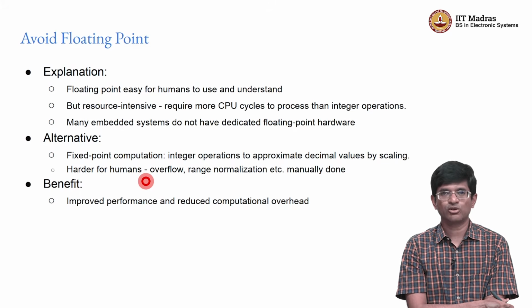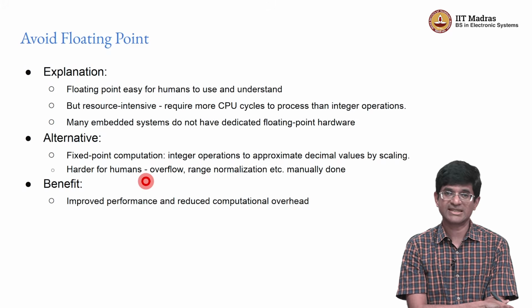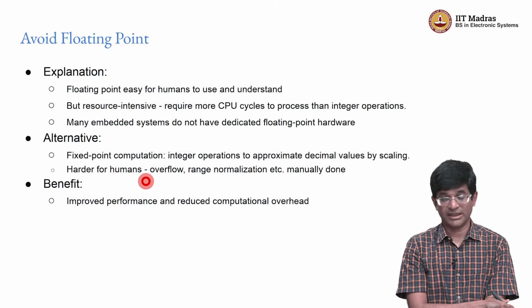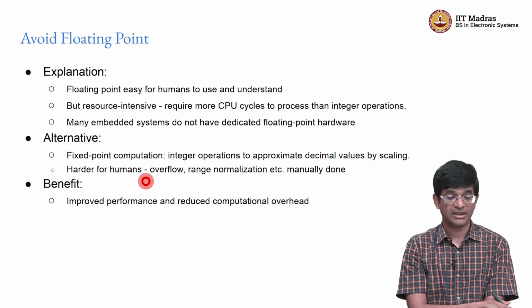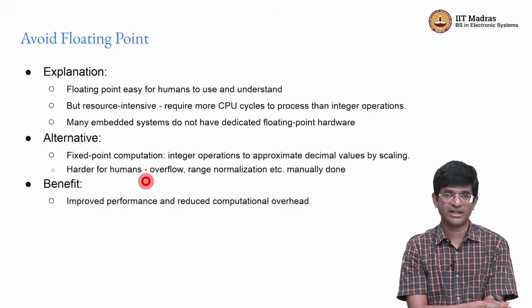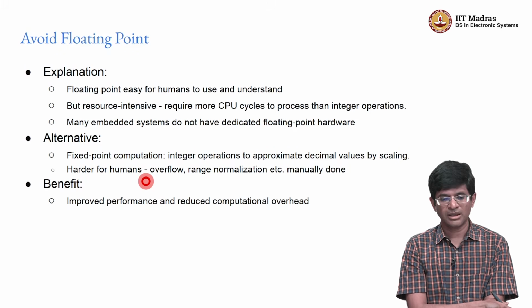In certain cases you might actually have a microcontroller that does not even have support for floating point, which means that if you use the float data type, it will still work, but it will have to emulate the behavior of floating point completely in software. That can turn out to be very expensive, many clock cycles, possibly hundreds of clock cycles for something as simple as adding two numbers together, right?